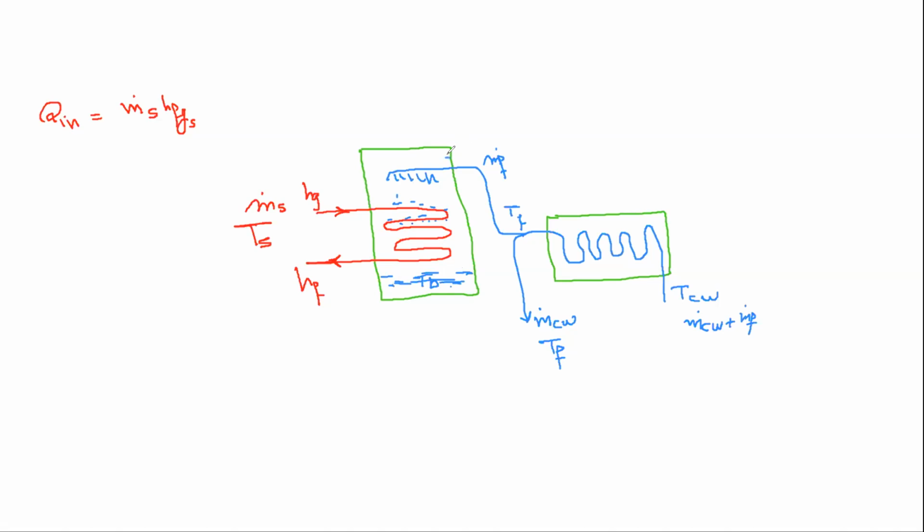We have a mist eliminator here to prevent the seawater from being carried with the vapor. And the vapor is going to take this quantity of vapor that has formed and it will come in here. So this is basically m dot vapor. Sometimes we refer to it as m dot distillate. It will condense here and we are going to collect it here as the product. So this is basically what we have in here.